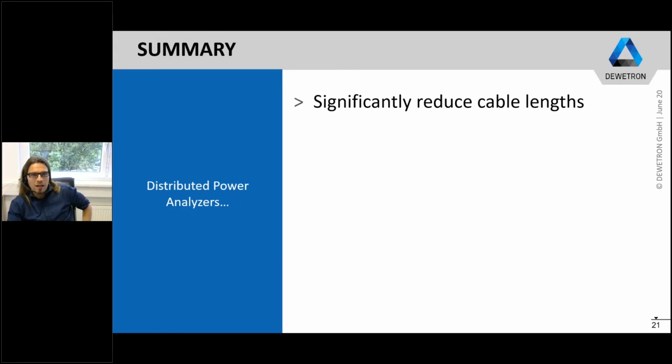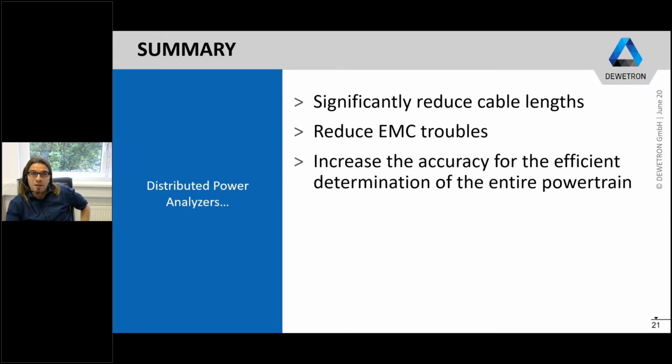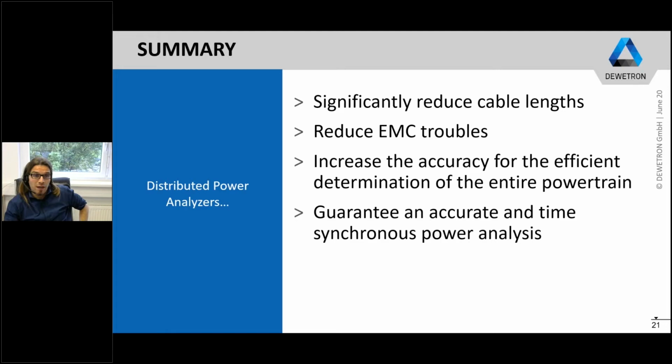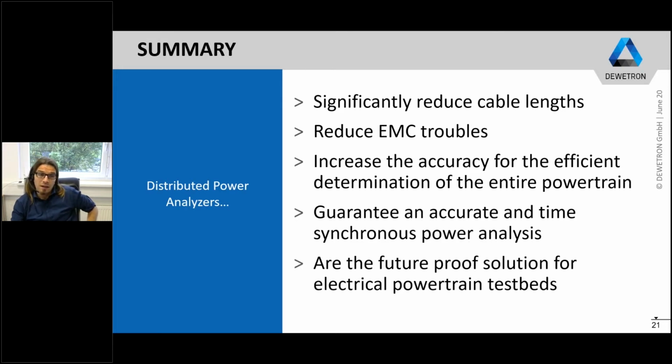So distributed power analyzers significantly reduce the cable length, specifically the sensor cable lengths, reduce EMC troubles, increase the accuracy for the efficient powertrain analysis in the electrical and in the mechanical domain, guarantee an accurate and a time synchronous power analysis, and last but not least are, in our opinion, the future-proof solution for electrical powertrain testbeds. So much for the theoretical part.